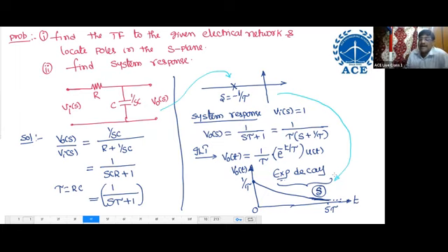In case many poles are on the negative real axis at different locations, what happens? You will get approximately exponential decay only. The approximate nature is exponential decay. Poles decide the system characteristics 100%. That's why the characteristic equation is defined as the denominator of the transfer function.